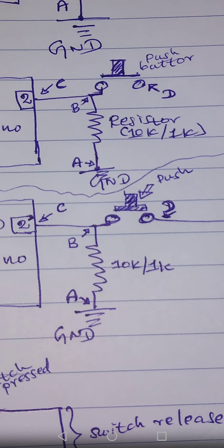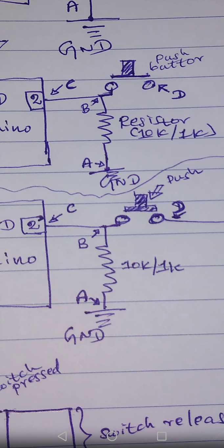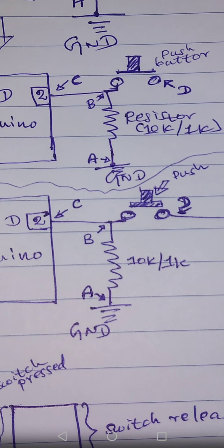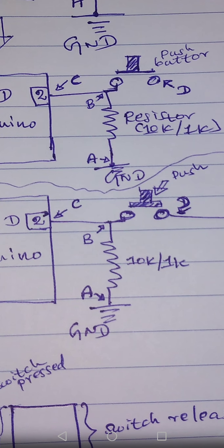Okay. So now we can understand, if we digital read the values, if the value is +5 or high, we understand the user has pressed the switch. Whatever logic you want to happen if somebody is pressing the switch, you can implement it using an if condition. When we study the if condition, we will take this same example. That is another thing.